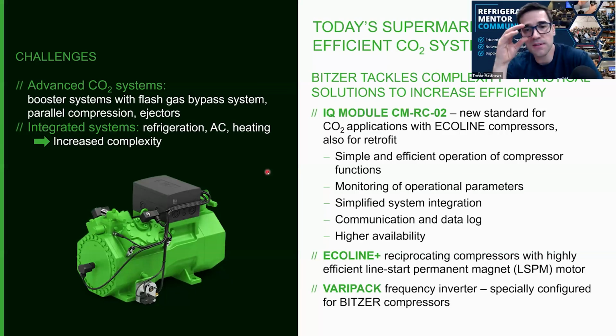The challenge. So I have a question on that, because this is one of the things that for CO2 everyone was worried about: the ambience being so warm. You know what I mean? It's always hot out, and CO2 doesn't work as well in hot climates. We know now with parallel compression and ejectors, it can be used all around the world.